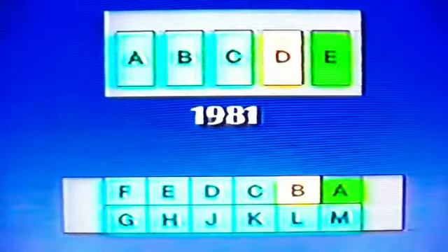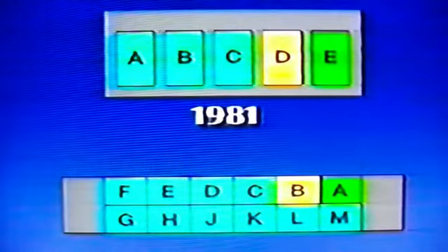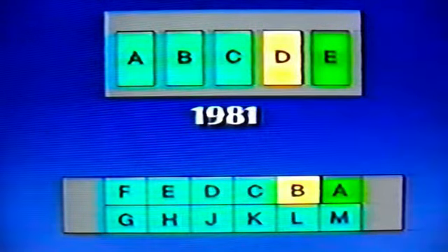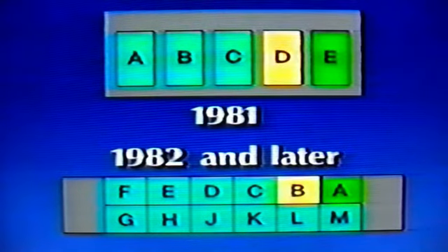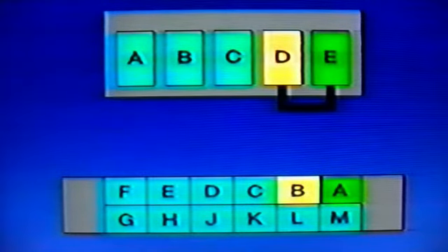In 1981 model cars, a 5-terminal connector is used. Although this was changed to 12 terminals in 1982 in newer cars, they still use 5 terminals on the top row with carbureted engines. To check for stored trouble codes, you take a spade lug or jumper wire and go from this terminal to this one on the connector, or from here to here on the 12-terminal model. Essentially, all we're doing is taking this wire to ground.